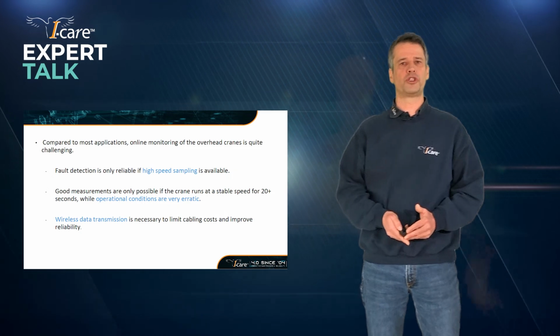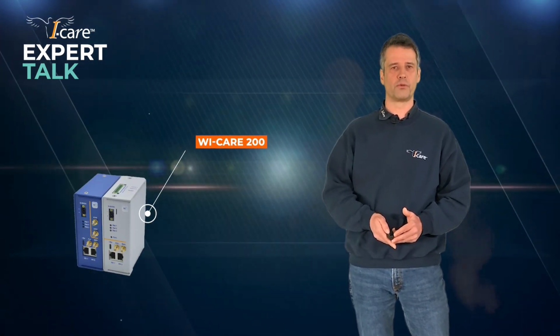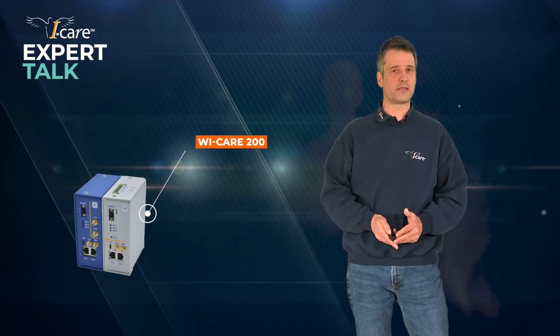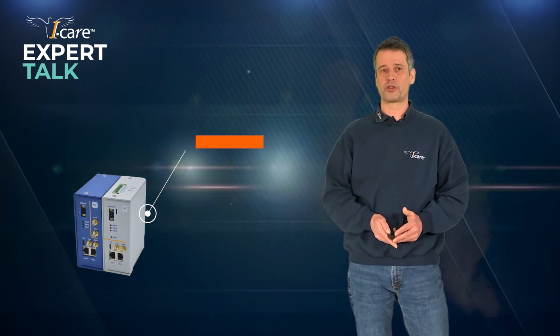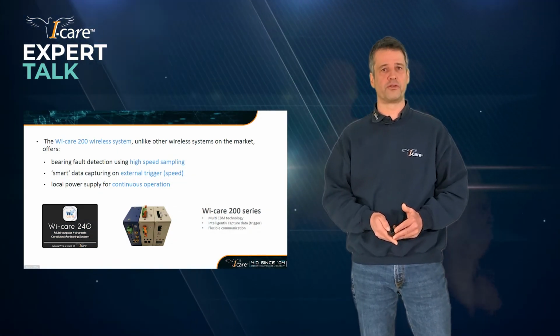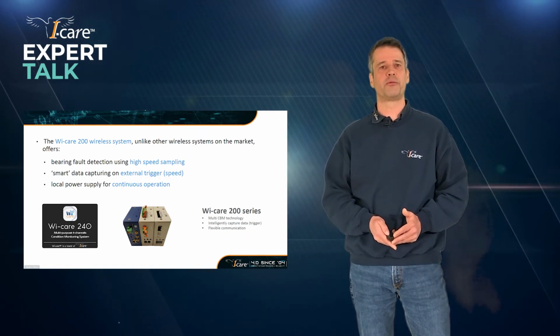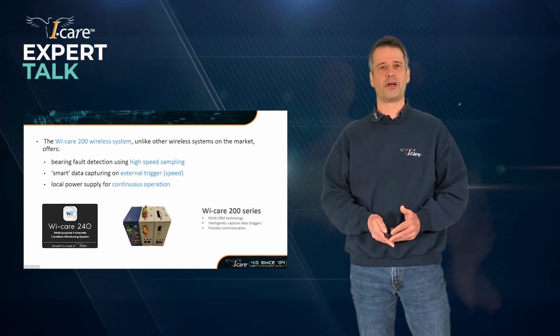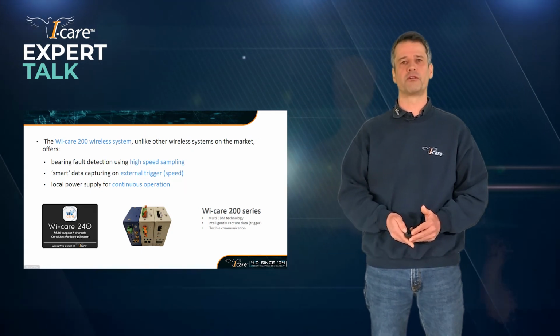So the system that we chose to provide these monitoring techniques is the system that was developed internally at iCare, which is the WeCare 200 wireless system. That is a system which indeed provides the high-speed sampling techniques. It also allows us to perform data capturing on external triggers, which means we only take measurements when the crane is in a condition where it is suitable to do so. And third, it provides local power supply, which is necessary for the continuous operation of the online system.